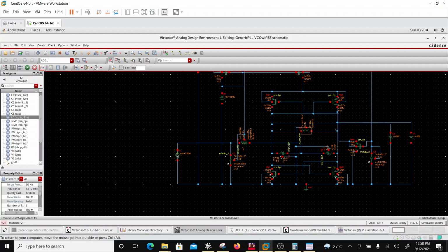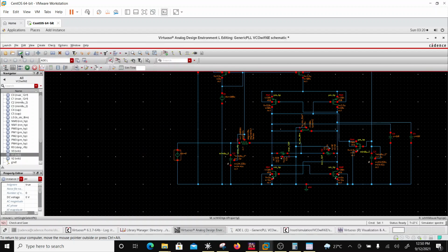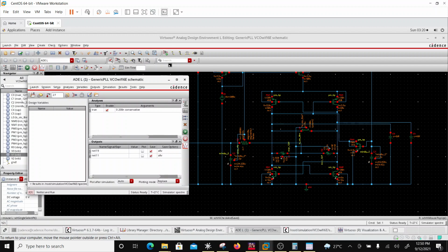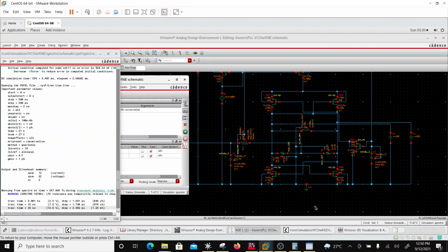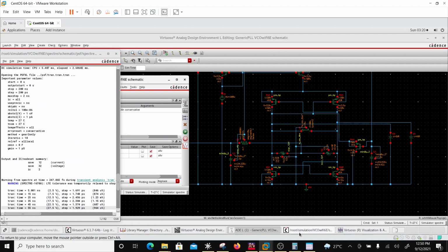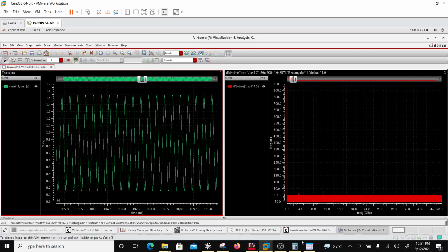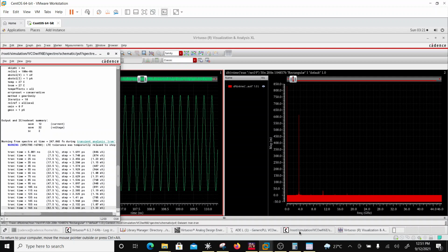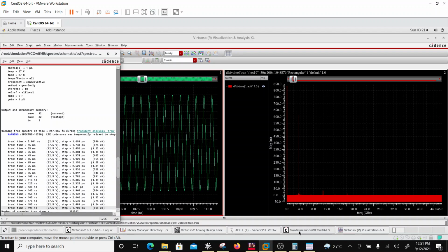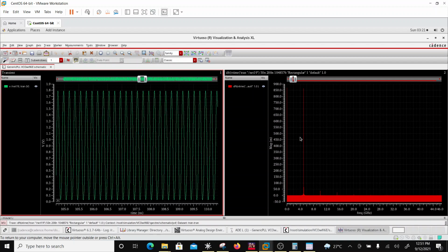Check and save. And here I'm going to look at the higher frequency limit of 0 volts, right? Tuning voltage of 0 volts. Check and save, and I'm going to simulate this. Just want to make sure that I get the band with the loading, right? Okay, let's see, what do I have here? And this is 5 gigahertz, right?